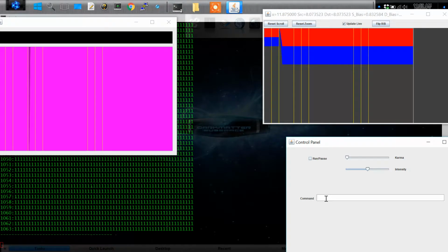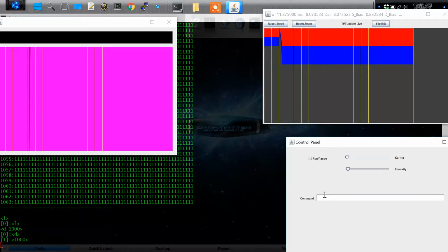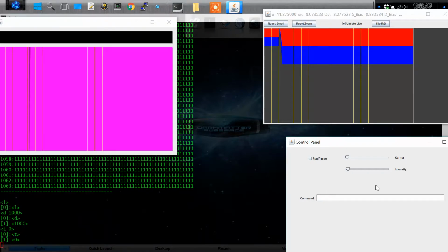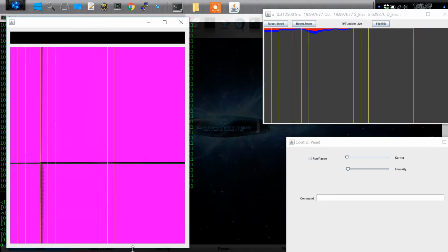So this is a system that can actually differentiate, and we can see a little clearer what's going on if we load it in. Let's set a delay of 1,000, and let's run test 0. Our input is over here, and it goes low for 4 ticks, and then high for 4 ticks, and low for 4, and high for 4. And you can see the input over in this region near our scan line, and you can see the output developing here.